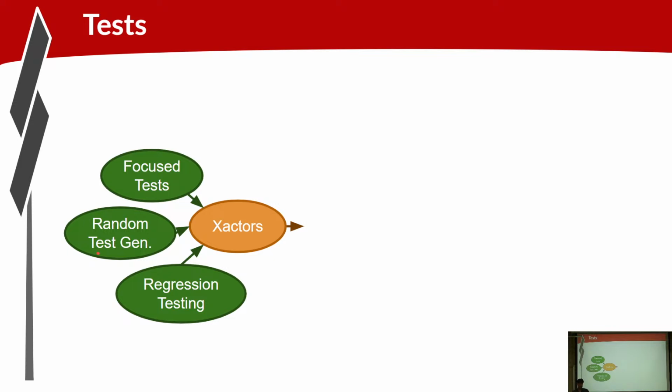We have random testing and varying levels of randomness in the testing, right? So the random testing, of course, is trying to give us a smattering of activity in the chip, where the focus tests may be drilling down into a very specific gnarly corner and trying to exercise something that if you just throw random stimulus at a design, you're unlikely to hit. Also, the focus tests tend to be easier to write, so you might do a lot of that early on for the path clearing kind of activities to make sure things are generally healthy enough to apply the random stimulus to, right?